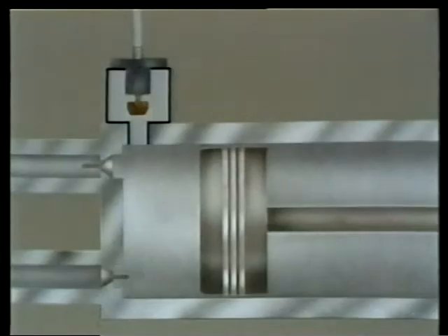When receiver pressure reaches a certain point, pressure in the air line opens the valve, connecting the clearance pocket to the cylinder. Now, this creates an extra airspace in the cylinder. So on the discharge stroke, only part of the air in the cylinder is forced out through the discharge valve. The rest of it stays in the clearance pocket. So the compressor's flow rate has been reduced. Some reciprocating compressors are made with as many as 4 clearance pockets.